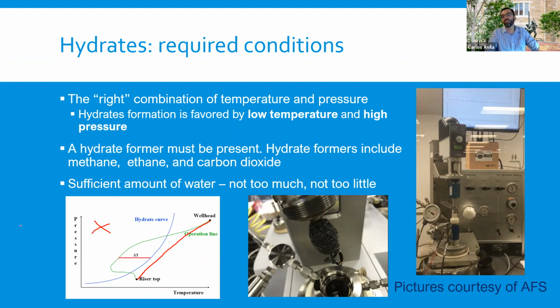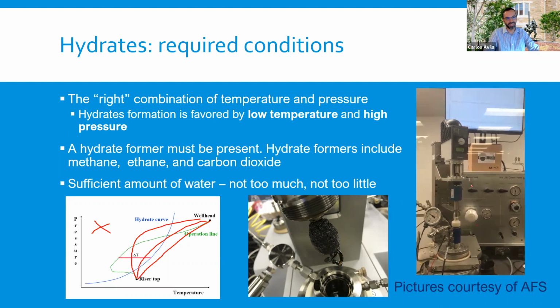But let's suppose that something went wrong topsides and they have to shut down the operation for a few hours and your fluids start to cool down. The temperature profiles start to drop and you start to go inside these hydrate regions. So that's when you need to do all your studies and transient thermal analysis to understand your fluid and how many hours you have until you need to take an action and take other measures. So here's a video of that experiment with the static mixer characterizing hydrates.